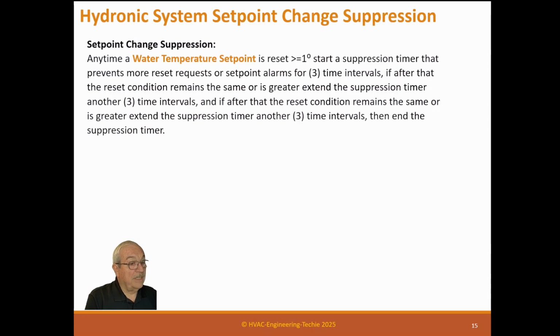So what happens is it keeps asking more and more and more requests, but the system's not responding. So what it'll do, it'll drive your temperature requests all the way to maximum, whatever that is, or minimum, whether your temperature's going up or going down. And that's not what we want to do. That would increase energy proportionally, so we're not doing that. Now, eventually the alarm will trigger, and the operator will figure it's not working, but we don't want to drive these resets completely out of sight because of that.